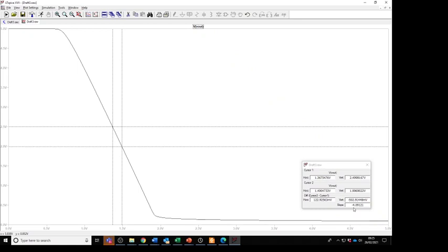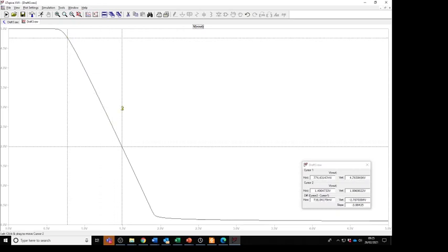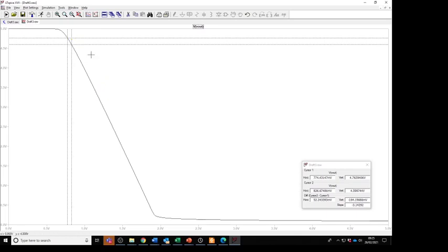So at the moment, looking at that bit, the average slope between there is 4.09. So we would expect to get a gain of roughly 4 off this amplifier. Now, if we biased it at a different point, the slope at that point there is 3.14. So if we biased at this point here, not only would we not be able to move very far in terms of our output, but we've also changed our gain.